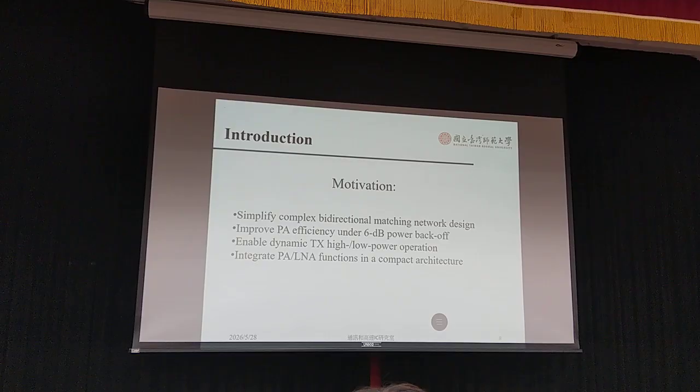Second, we want to improve PA efficiency under 6 dB power back-off operation. This is important because real wireless systems do not always transmit at maximum power. Third, we want dynamic high power and low power transmit operation. Finally, we want to integrate PA and LNA into one compact architecture.